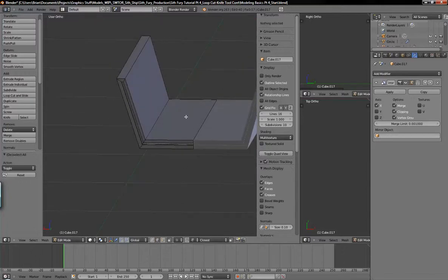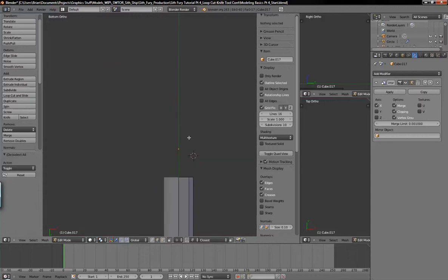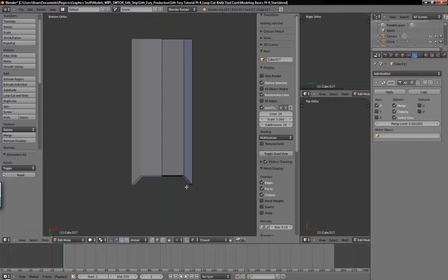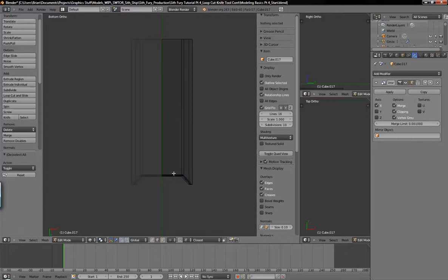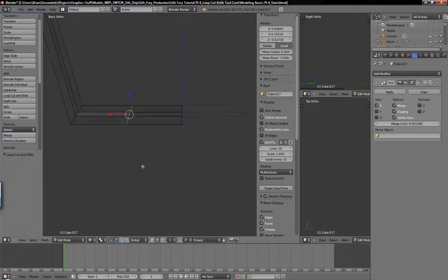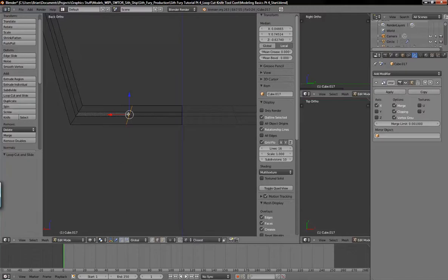We want to cut the ramp opening here. So we hit Control 7 to go into bottom view. Scroll out a bit, and we want to do a knife cut first for the edge of the ramp. Because if you do the loop cut and then hit Control 1, you see you have an angle here. You could do that if you wanted the edges of your ramp to be angled. I'm just going to keep it the way this is, and this is vertical. So we want to do a knife cut, so it's a clean straight cut there.